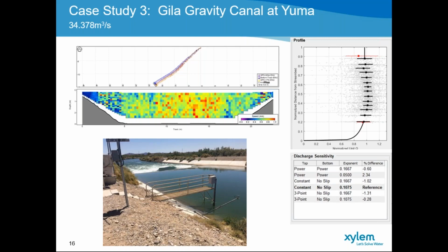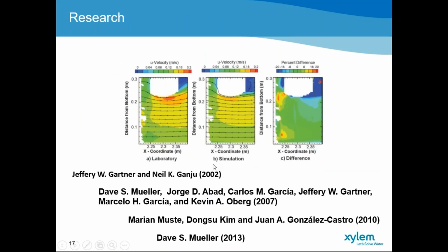So your velocity distributions change depending on the flow releases in the channel. So it is important, especially at this specific channel, to verify the extrapolation with almost every single measurement exercise to make sure that the correct extrapolation is applied.